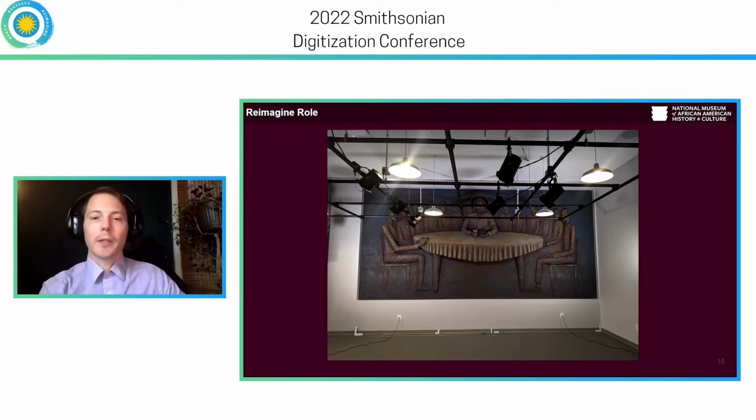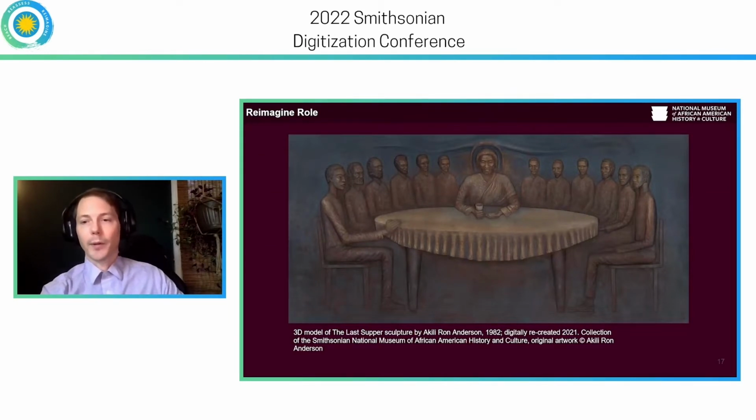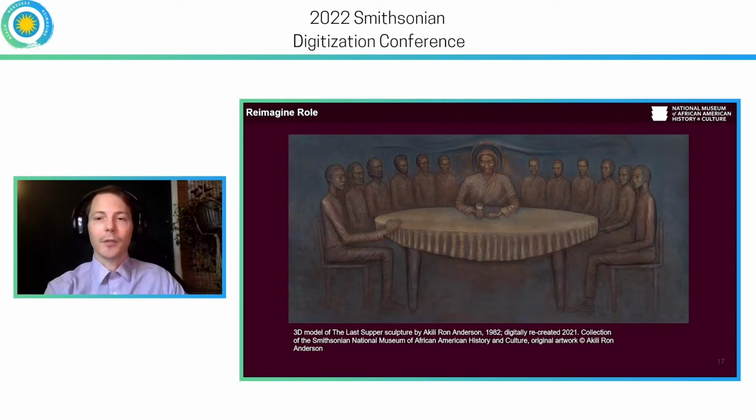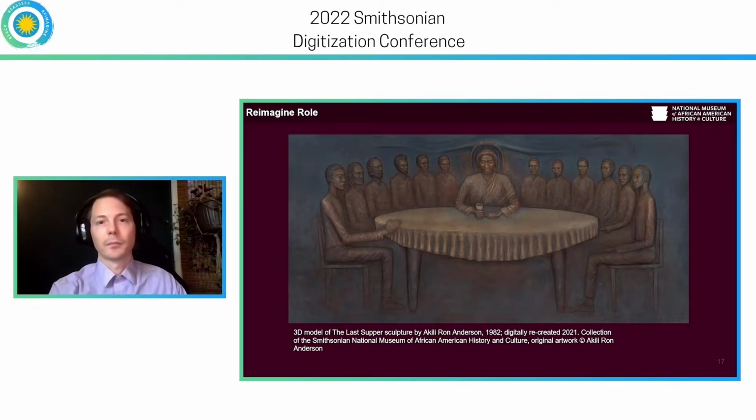So there is no good way to capture a clear single image of this object using a normal 2D imaging workflow. However, I can use photogrammetry to capture this object from points of view that are not obstructed and then output a 2D image from that data using 3D tools, which is what you see here in the orthomosaic rendering of this object. This flexibility with 3D capture has allowed me to reimagine how I would create 2D imaging for publication or research when normal imaging workflows are out of the question. It has completely opened the door for reshaping our standards and our workflows.